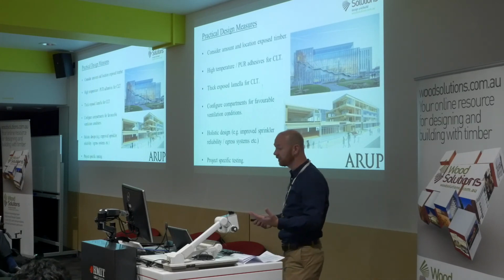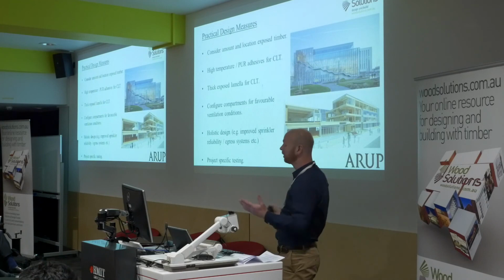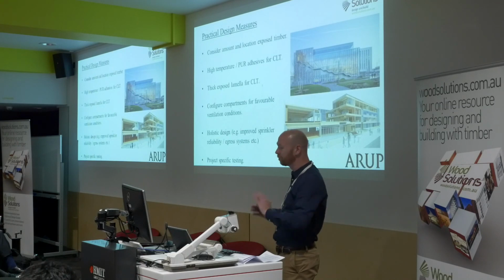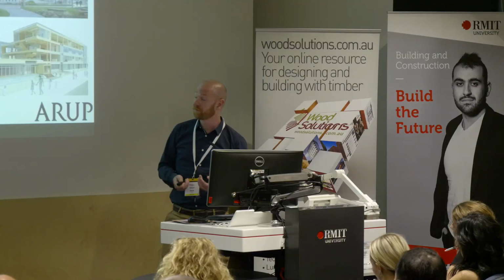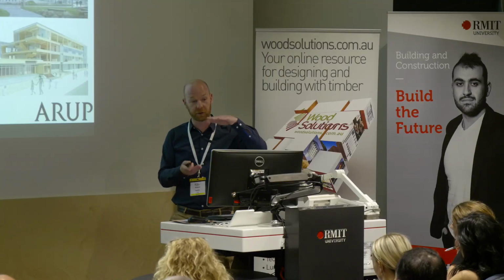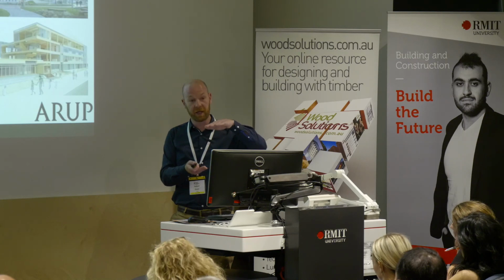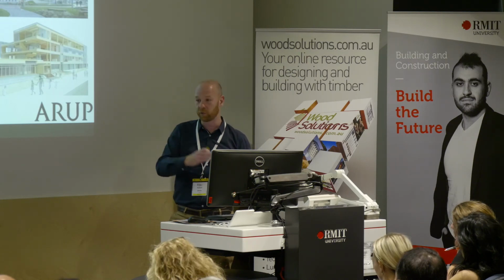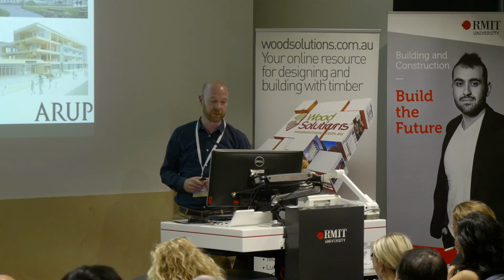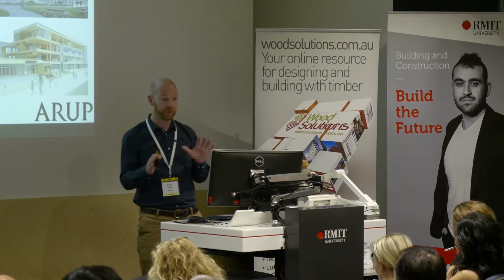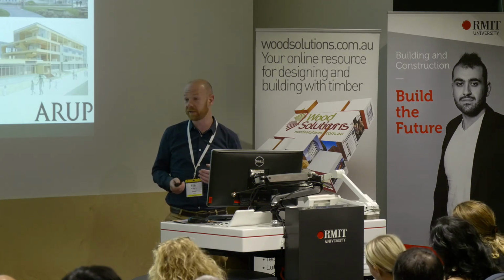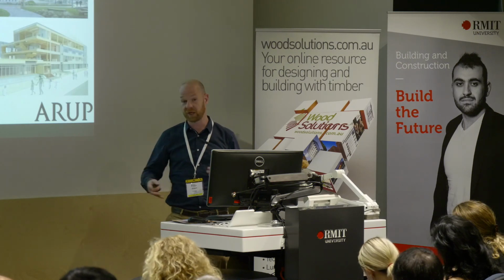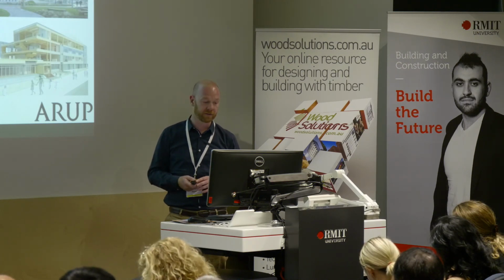Adhesives we touched on: with high temperature adhesives, we can get rid of delamination, and it makes life a lot easier. Not saying you can expose everything, not even most, but some more. A thick lamella of CLT on the exposed surface, if you can design that in, then that maintains predictable fire dynamics for as long as possible. If you've got complete control, if you're right at the beginning of the project, you can configure compartments to have favourable ventilation conditions in terms of compartment size, fire load, and opening size.